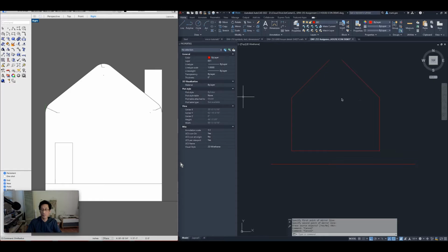Okay, so then what we can do is come over here to AutoCAD and do a fillet, F, and before I click anything, I'll change my radius setting and do a radius fillet of 24. So type in 24, enter inches. And then since I want to do 3 of these, I'll use the multiple option here. So M, or since my mouse is there, I can just click. Now it's asking me to select first object, and I can just go around here, and there, then that, and that one, and then that one, and that one.